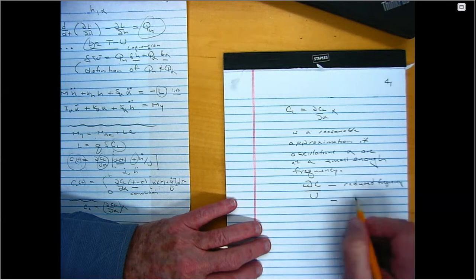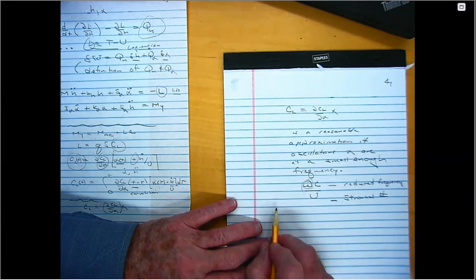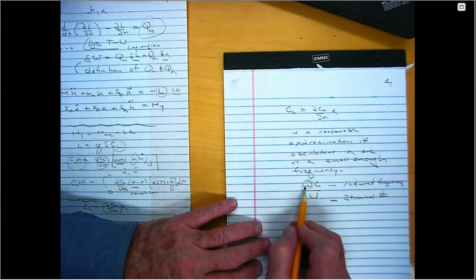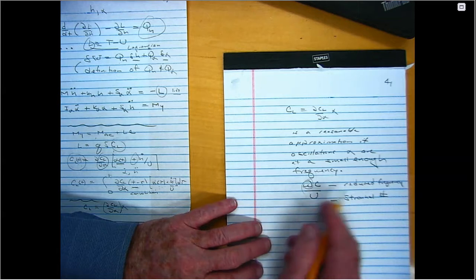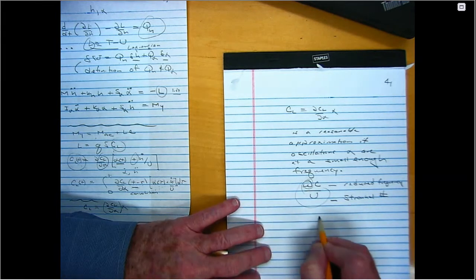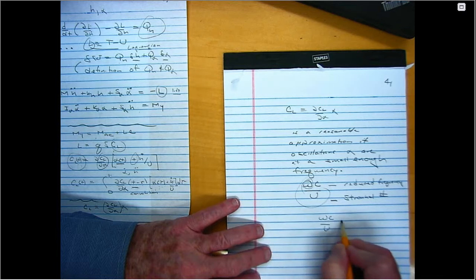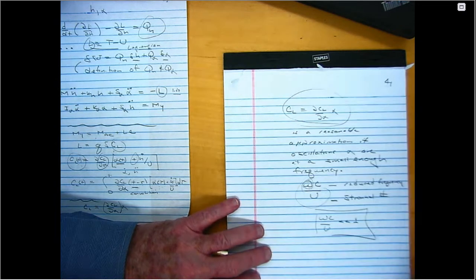Sometimes, in the literature, there's a guy named Strouhal, and sometimes it's called the Strouhal number. Except using the Strouhal number, you take this frequency, which is in radians per unit time, radians per second, and divide by 2 pi, so it's in hertz. Which is unfortunate, because if you throw away the 2 pi, you lose a lot of the essential physics. It comes from this. It's really when this number is small compared to 1 that this is a good approximation.